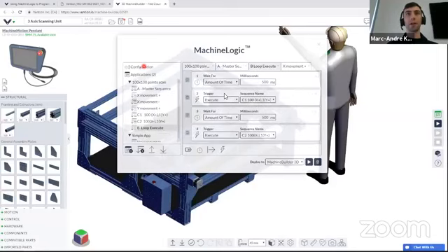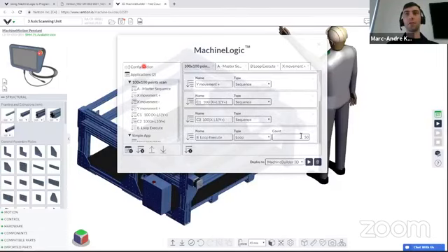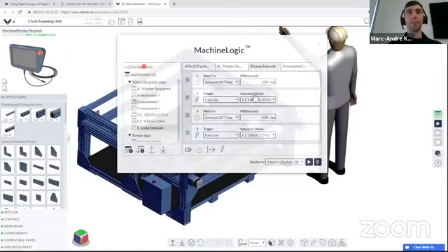The B loop here is actually going to be used 50 times. The reason is that we're going to cover two rows of holes using this loop, so 100 divided by 2, 50. And in this B loop, as you can see, I'm waiting in between different moves, and I will execute my C sequence, which is 100 times X. So I'm going to move in the X axis 100 times to cover the 100 holes. And then at the end of this movement, I want to move by one row up in the Y axis.